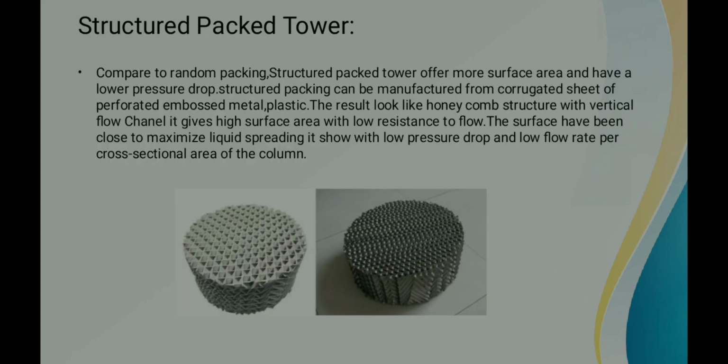Next, we come to a structured packing tower. Compared to a random packing, a structured packing tower offers more surface area and has a low pressure drop. A random packing is randomly placed, whereas structured packing has a uniform structure when placed in a distillation column.